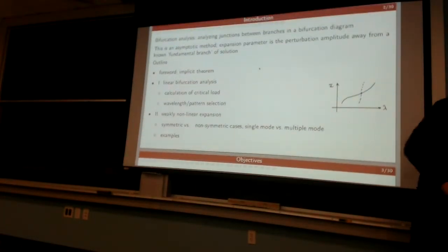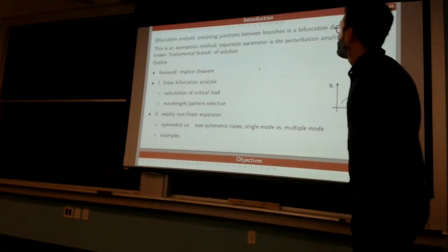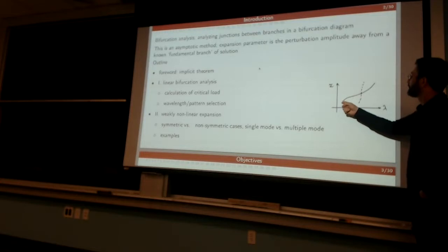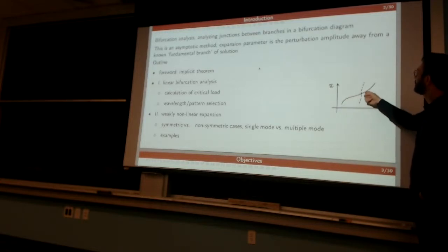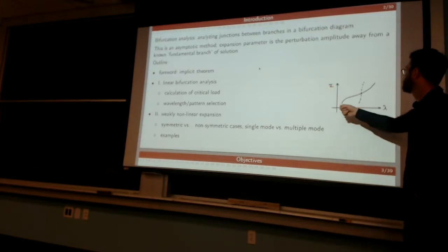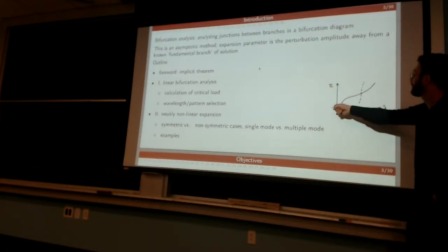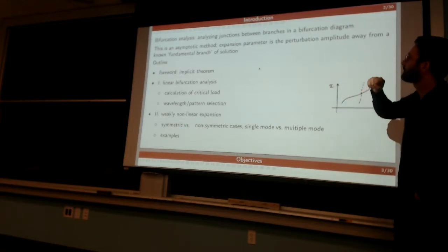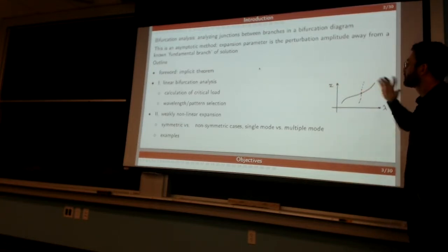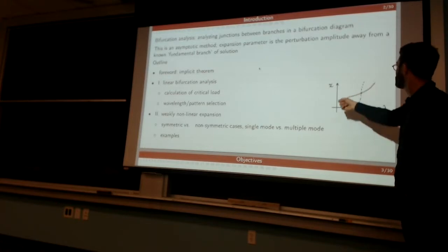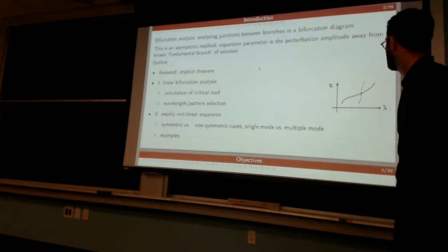Okay? So essentially, the bifurcation analysis is concerned with finding bifurcation, that is, branch crossing, when you're in this phase diagram. So typically we have a system that has load parameter lambda, and x would be the state of the system. And today we'll be assuming that we know one set of solutions. It's called a branch because it appears as a curve in this bifurcation diagram.